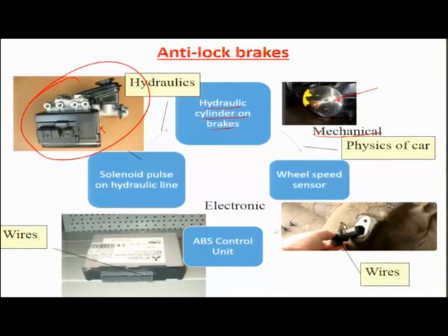There is of course a wheel speed sensor, which is based on some mechanism for sensing, where mechanical motion is transduced back into an electrical signal, and there is this ABS control unit, which will determine how much pressure goes to whichever wheels, in terms of pumps getting 4 different oil routes to send to the different cylinders, which will create the pressurization action at the mechanical level, or at the wheel level. So it's a combination of the hydraulic cylinders which will create some kind of mechanical output.